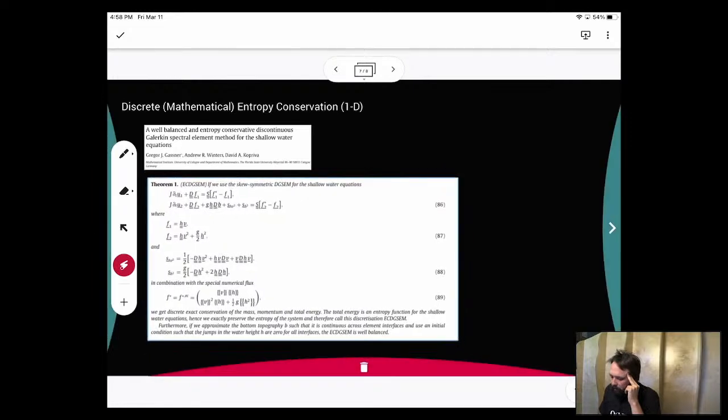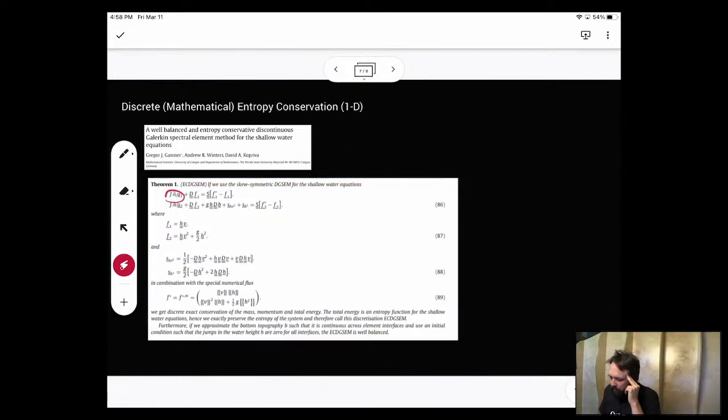So what they're calling U1 here, let me get that to go away. U1 is the total fluid thickness, so eta minus h, or basically the water column height. We have a conservative derivative of the volume flux, and then you end up with boundary terms coming from those Riemann solvers. For the momentum equation, it turns out that the skew symmetric form when you discretize ends up being exactly the conservative form, plus these additional product rule errors for the momentum flux and the volume flux on the right-hand side.